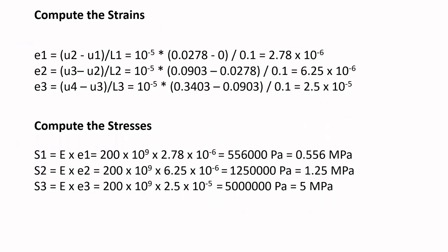And finally, from strains we can compute the stresses. The stress in element 1 is given by S1, that is equal to Young's modulus times the strain. Young's modulus is 200 into 10 power 9, and if you multiply it with the strain value, you are going to get the stress, and the value will be in SI units, that is pascals.